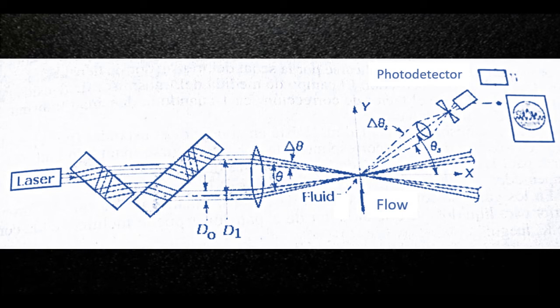The laser flow method is based on the emission of a laser beam focused into the fluid at the point where the speed is to be measured. These rays are scattered by the particles of the fluid, thereby inducing a Doppler effect signal corresponding to the frequency of the reflected light, a signal that is captured by photodetectors and that is directly related to the speed, and therefore to the flow for a pipe of given section.